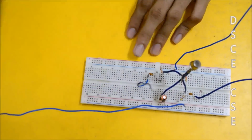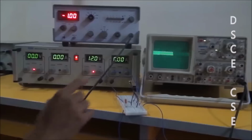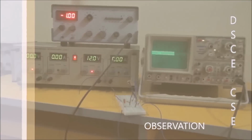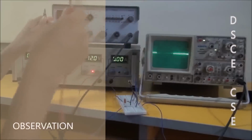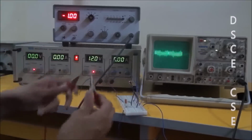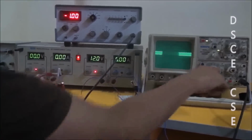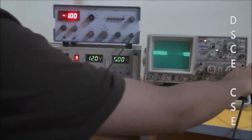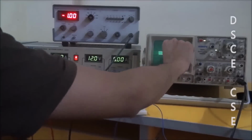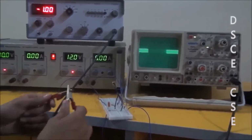Now that the circuit connections are made, we connect it to the CRO and signal generator to get the output. We need to set the VPP at 0.2 volts, and then we connect the input and the output. The output of the signal generator is connected directly to the CRO by crocodile pins. We set it to 50 millivolts in the dial, and then we make that coincide with one box so that we have 50 millivolts of peak to peak voltage.